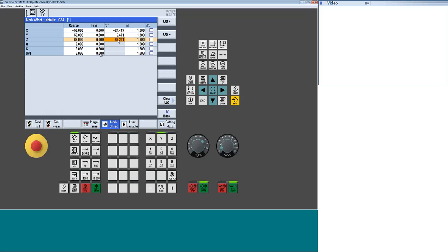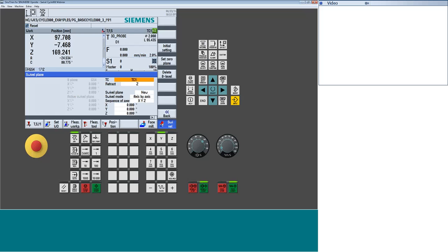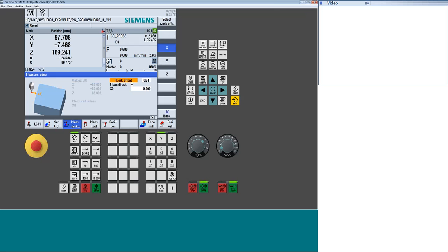And everything is set. So once we've gone in, we've rotated, we've oriented, everything's straight. Visually on the machine, the part looks straight. Now the final step in part setup would certainly be going to our measure workpiece, and then maybe even picking an edge kick, finding the center of a bore. My norm would be finding the center of a block, right? Because typically I like to work this on a 5-axis, the center being 0, 0. But you'll just go through the steps you normally would in establishing the part 0 now at this point.